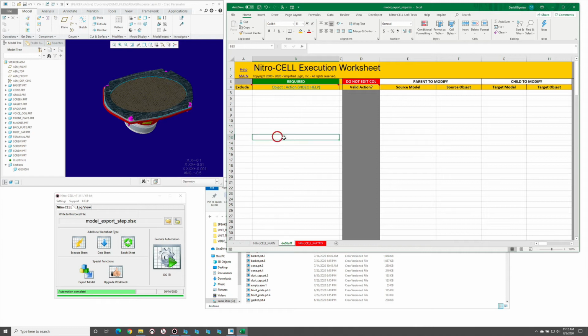Talk about exporting step files. This command is actually pretty handy. So if we say export step for the model function here, this will actually take the active model as the default, and you can also give it a new name or a subdirectory and a new name to write to. And then also you have these other options that you can specify regarding the step.